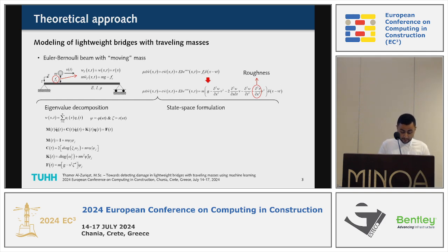This vertical displacement is a convolution between the space function phi and a temporal function called q. And it's also the summation for all the eigenfrequencies from the first to infinity, but for our civil engineering application, we mainly consider the first 2 or 3 eigenfrequencies. In our case, we took the first 2 eigenfrequencies.